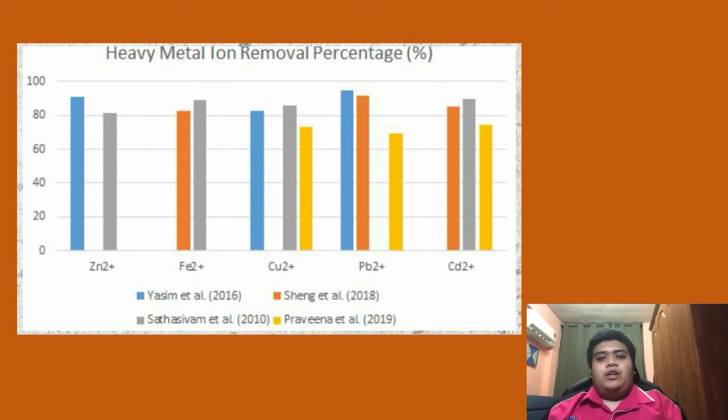By being capable of absorbing all of these heavy metal ions, it can improve the quality of the palm oil mill effluent so that it can be discharged after the treatment with banana stem bioadsorbent. In wastewater, microbial activity and biological wastewater processes can be affected by high concentrations of heavy metals. Thus, removal of heavy metals from wastewater can also help to reduce the chemical oxygen demand.